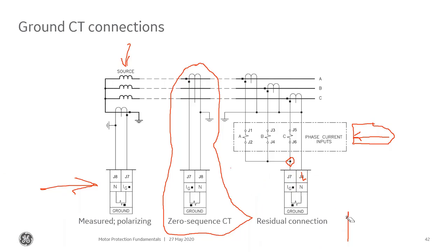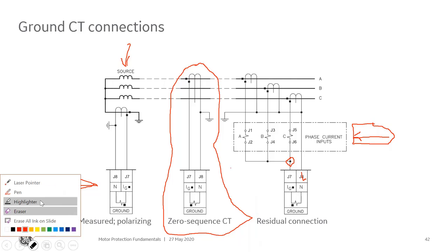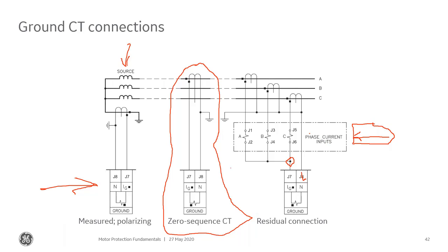They're the same here because the calculated quantity, whether we're doing vector calculations inside of the relay or whether we're doing it with this wiring connection, is basically going to be the same. So again, that's why I like to do a neutral overcurrent when I have that solidly grounded system, rather than complicate my wiring and having to wire the ground into it.